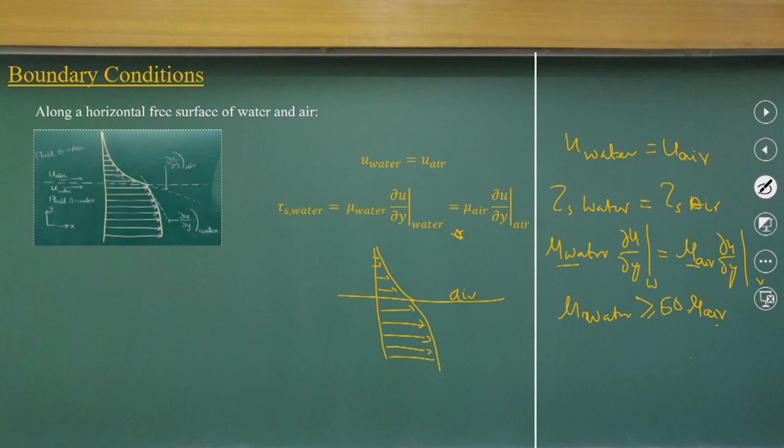Now, try to understand how we are getting this. That component has to be very small. Very simple boundary conditions: the pressure of the liquid is equal to that of air, and shear stress becomes 0. Just try to interpret these components. The shear stress acting at this free surface should equal 0 or be very close to 0. Then we can solve these problems.